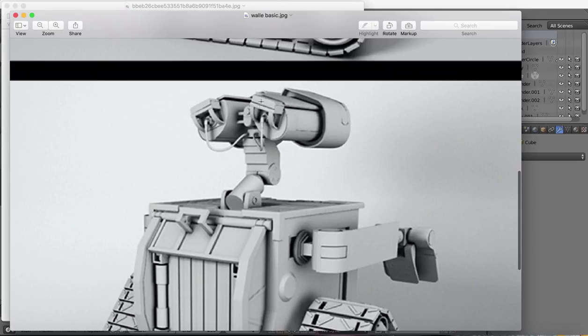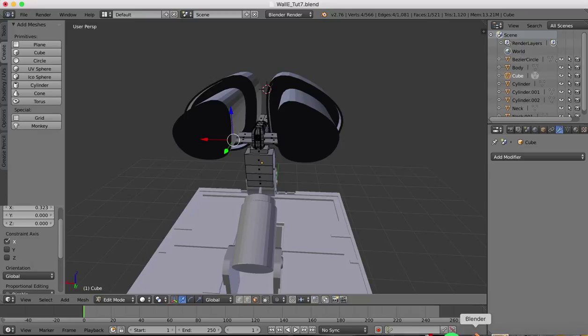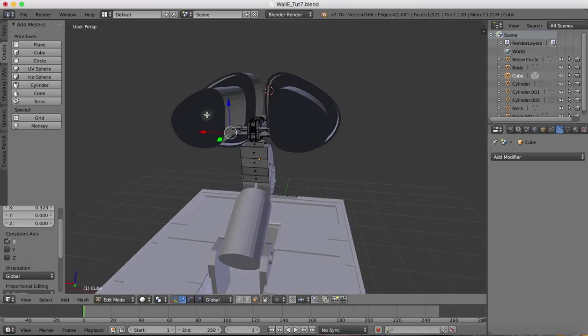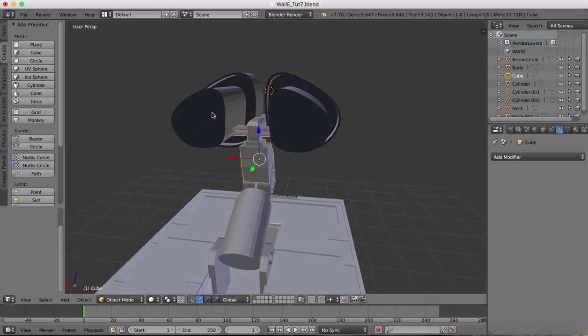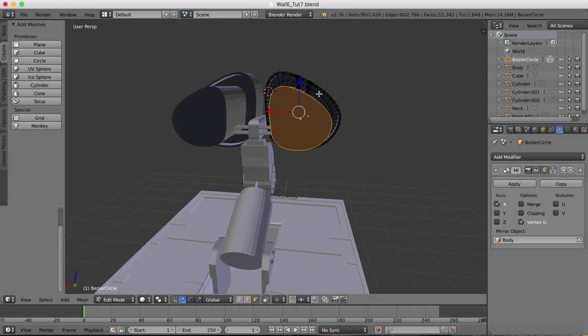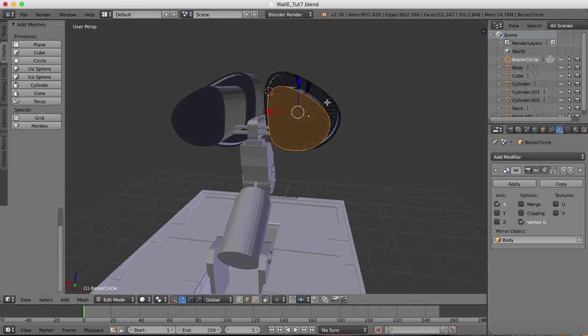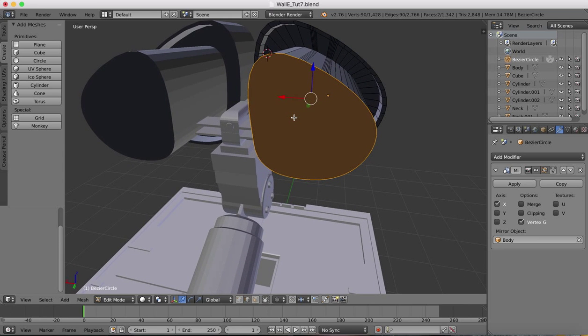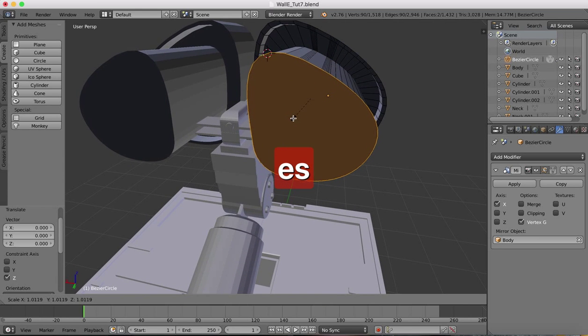I'm going to work on this area here and this curved part that goes at the back. So we'll start off with creating the flat top part in the box that goes behind it. We've also got a slight recess there at the back, which we're going to add in as well. So go back over into object mode, we select our object, over here into edit mode, make sure we selected all those edges, E to extrude, S to scale,